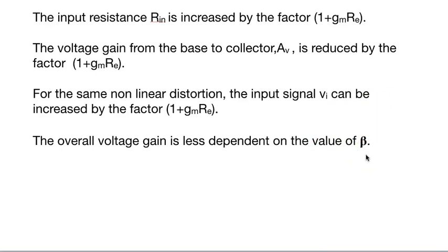And that's a good point, because beta is a quantity which changes with temperature, and that sensitivity to temperature will affect the normal working of our device. To reduce that effect, we attach a resistor at the emitter, with a decrease in gain, but we make the whole circuit gain beta free.